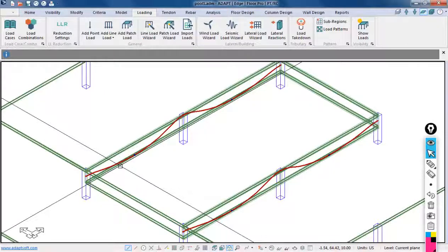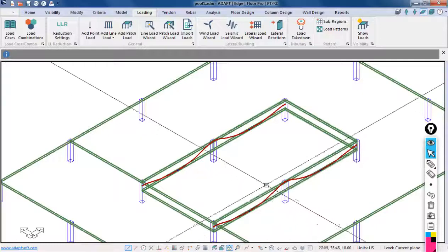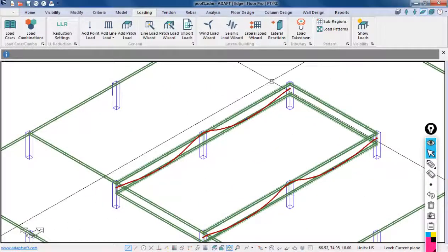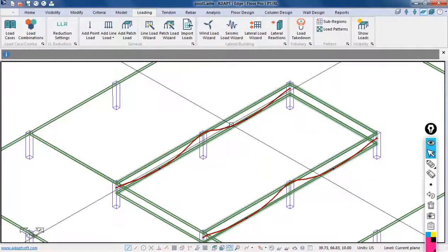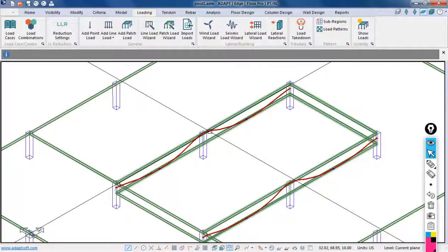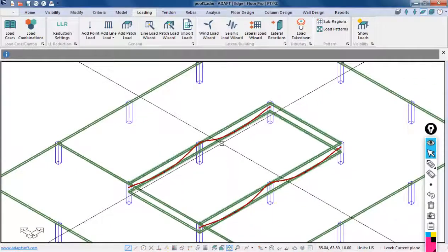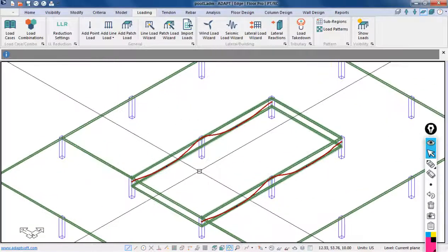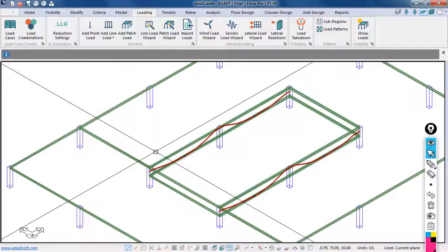In modeling walls, it's a little bit different. With walls, you can still model post-tensioning, but the post-tensioning essentially becomes external from the slab. The offsets and eccentricities are still recognized relative to the reference plane, so technically modeling PT with walls will work in terms of overall behavior and analysis results, but you still are unable to obtain design section results with a wall.